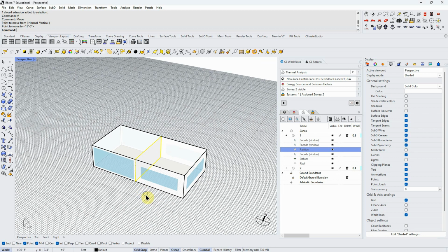The point is, though, you must have your zones. Some of you have complex forms. A zone is just a box of air, and all the boxes of air have to touch. They have to be coplanar. If they're not, that's going to screw up your model. You need to build these slowly if you have a complex model, and just try them. Build one zone, see if it works, add another zone, and slowly build. If you have a problem, then you'll know where it is.